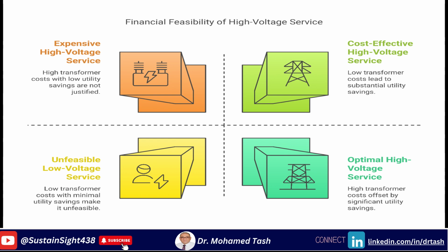And finally, the feasibility. The financial benefits depend on utility tariff structures and whether they offer significant discounts for high voltage service, the cost of acquiring, installing, and maintaining transformers, the proximity to the transmission line, and associated connection costs.